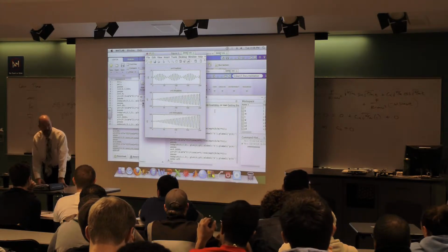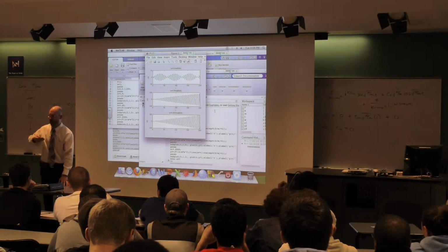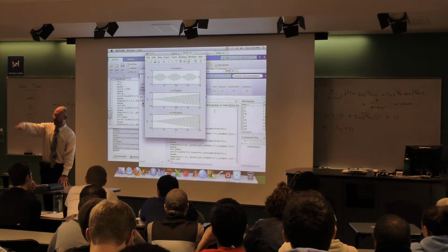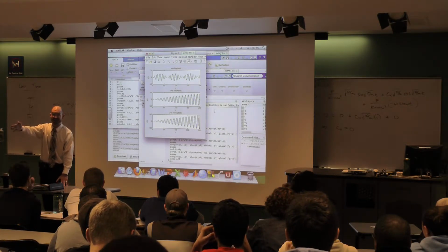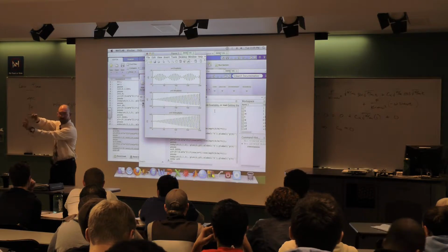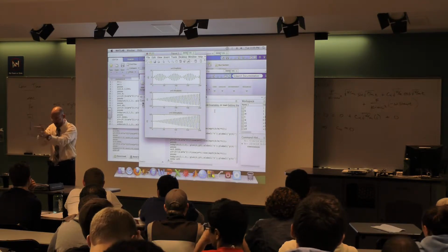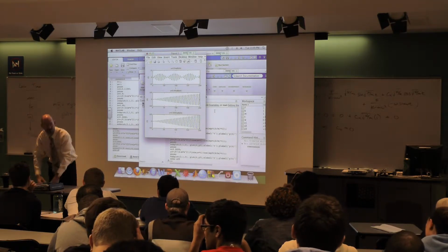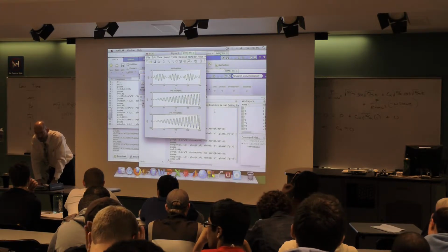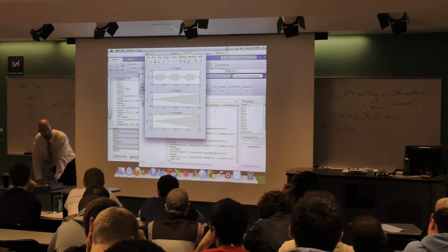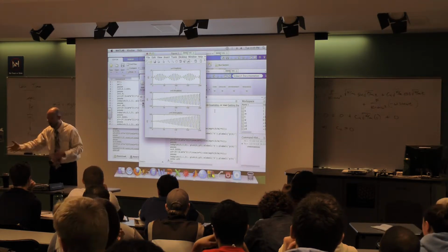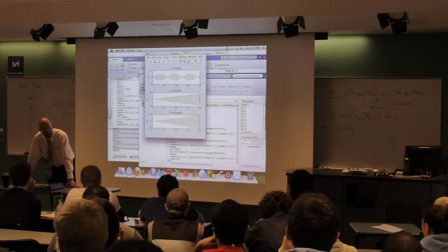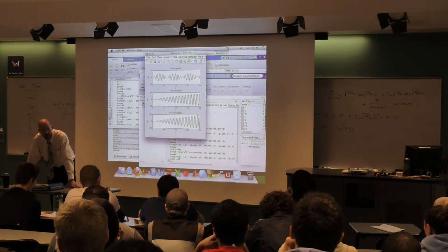of vibration. So they considered things like cars going across and it's going to vibrate up and down, but they didn't worry about the side to side, right? Or the twisting of the bridge. Any way that you could envision something oscillating or moving needs to be considered. Nowadays, we've got computer models of everything. Complete three-dimensional structural models of everything: cars, bridges, these things. So we can actually do vibration analyses that will identify all these different possible modes.